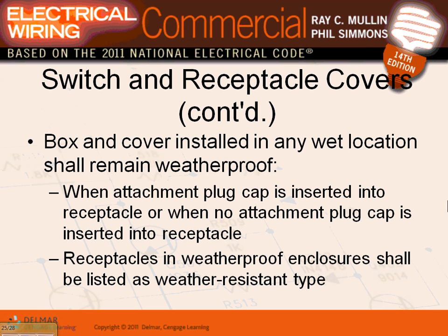We talked about if you have a receptacle or a switch in a wet location, it has to be in an enclosure, an in-use enclosure for a receptacle or a switch, special receptacles in-use enclosure.